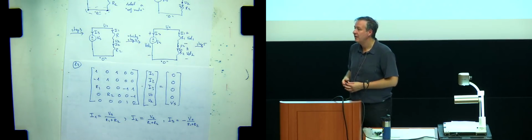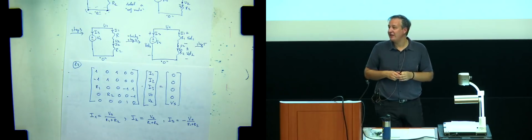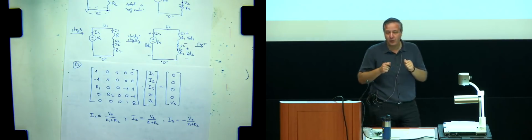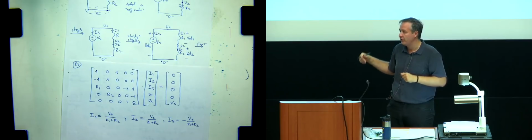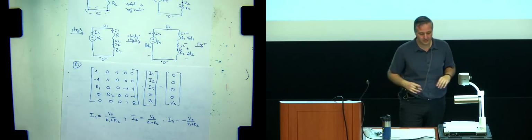In fact, I wanted it opposite so that you can get this negative sign and be confused. Because it really is a key point that you don't get confused if you get negative current in the circuit. It's completely normal. It just means you've assumed a different direction. So you don't have to work hard to figure out where the current's flowing before you label it properly. That's the wrong thing to do. You're wasting your energy, okay?